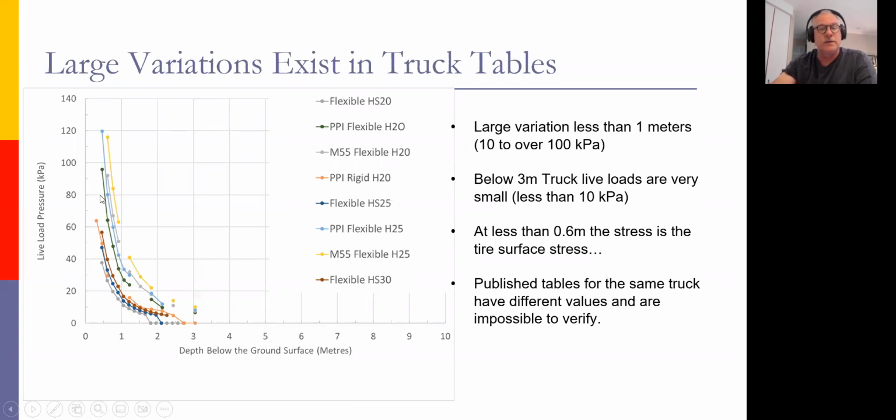So we'll take the load divided by the stress of the wheel. And that's what the maximum value will be from, say, 0.6 to here. So again, the spread really happens when we get to 1 meter, and if we go below to 0.6, that spread increases even more, and that's where that variation comes from. So that's why I say pick a table value. These are both doing the same calculations for the same truck, but the table values are much different.